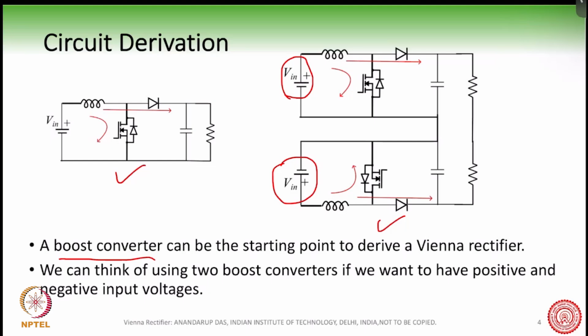Please remember that we are trying to derive, and I am here showing you the thinking process behind the development of a circuit topology. It is not exactly the circuit topology that we are going to use. So we are thinking in this way. So here we have this plus, and this is the minus, the negative portion of the boost converter, and these arrows here indicate the charging and discharging that will happen to these two inductors. Okay, we know this phenomenon.